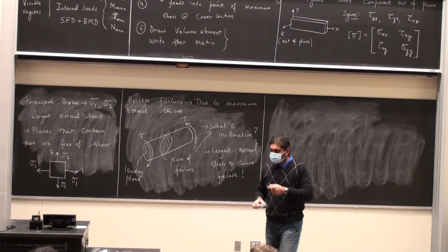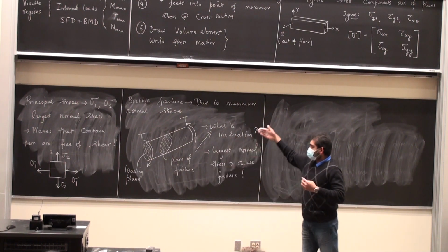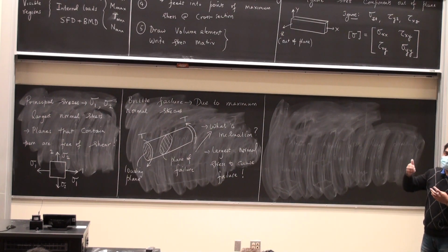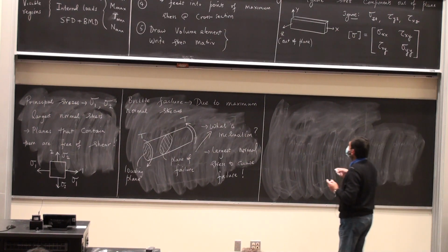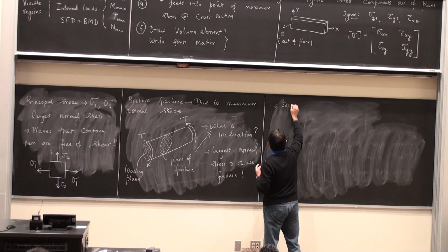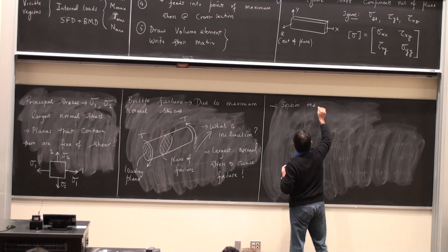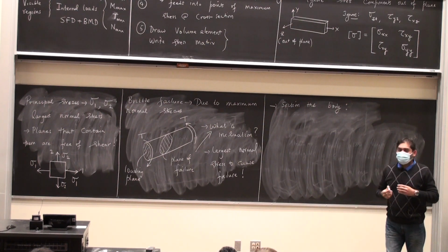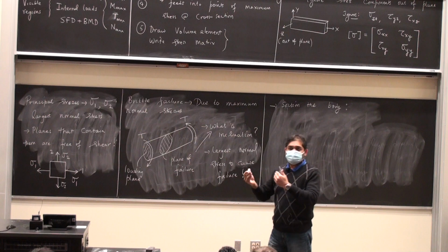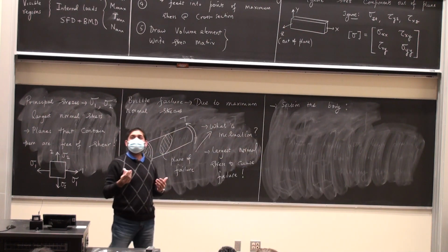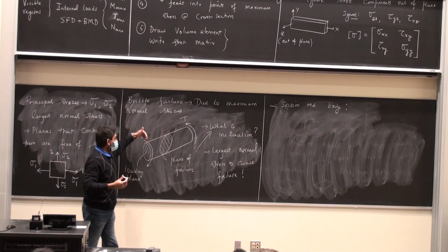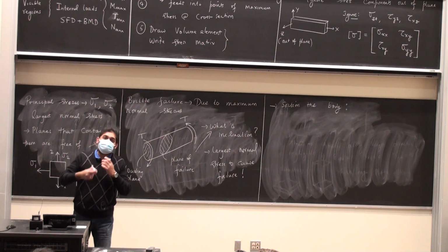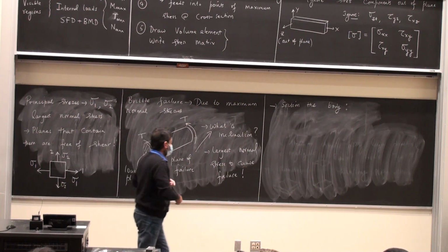Now I'm going to do the following. I'm going to cut open this piece of chalk and look at the state of stress on an area element on the plane of loading. So section the chalk. Now what's the internal torque? The internal torque is the same at all points because there is only one set of torque applied, so there is no discontinuity here. Wherever I section this body on the plane of loading, the torque is always going to be capital T. So there is no need for a torque diagram of some sort. Okay, so I break it open.